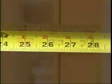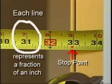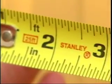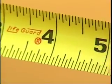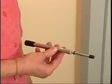To locate a fraction of an inch, read the smaller lines of various sizes up until your stop point. This will tell you your fraction of an inch. On most full-size, 1-inch wide measuring tapes, the inches are broken down into fractions. Each line represents 1/16 of an inch, starting with the first one after any given number or the start of the tape. Next is the door pressure gauge.